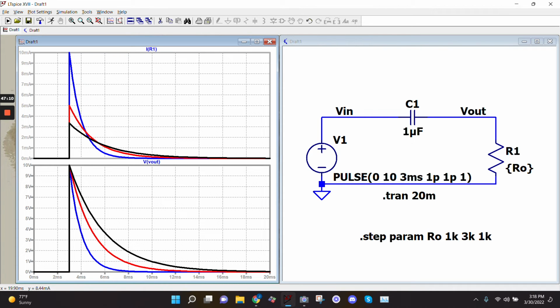Yeah. Can you make SPICE plot changes in tau for you if you're sweeping through different resistor values? Like actually physically plot, or calculate what that value is for you? I mean, you could. I think you can. You can do the math, but can you make SPICE do it for you? I think you could.